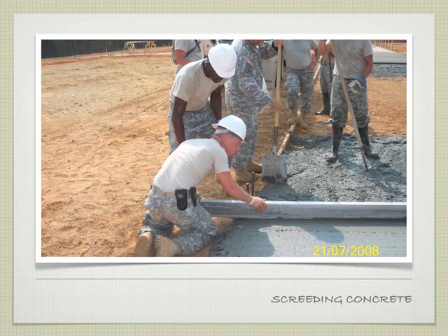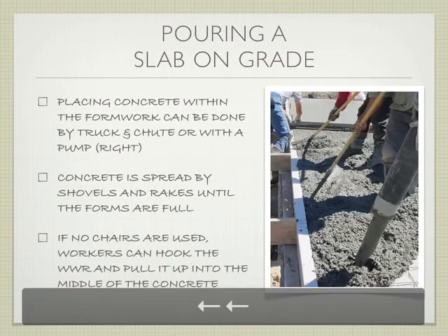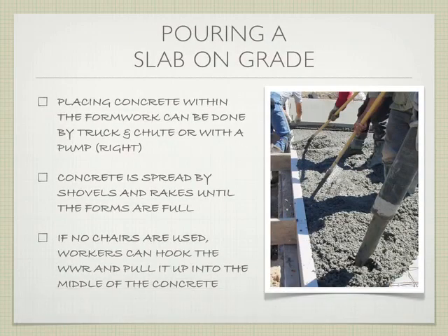Exactly. So as soon as you get the concrete into place, you're going to start this screeding process. And so the idea is that as you're doing it, and you can see it right here, as we're pouring concrete here, someone else is working on the screeding to move it there. So concrete is a lot about timing. And the people that have done concrete know this, and certainly the people who do it professionally are very good at getting the timing right, because you have to do things in certain orders so that it works smoothly. So if you've never worked with concrete before, when you pour your concrete beam, you will suddenly learn how important timing is. Did I get it in at the right time? Is it starting to cure too fast? That kind of thing.